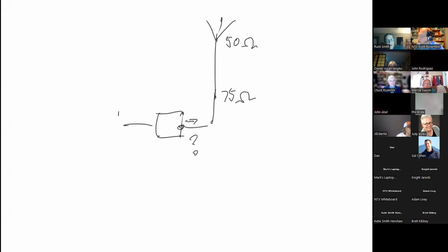Most transmitters have a characteristic impedance of 50 ohms. They want to see a 50 ohm antenna. They want to see 50 ohm cable. So we have this device, which is a matching device, which through the magic of capacitors and inductors and having them be variable allows us to add or subtract impedance from the outside world so that that question mark becomes something that is now predictable.